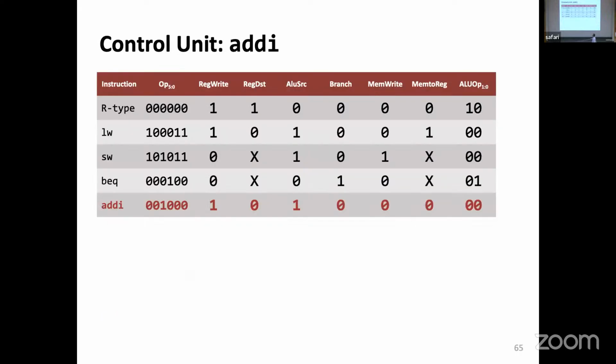So when I come here, this is a new instruction. Now you realize that, hey, it's an R-type instruction. It's very similar to this thing. I am using these things, but I am not writing to the memory. And voila, just by manipulating, let's say, the control path, I can have a different functionality. Was that too fast?